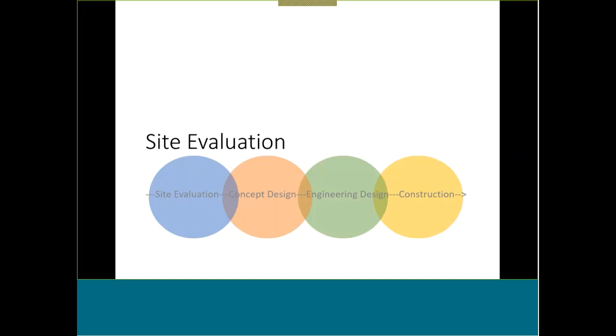So I think of site evaluation as being on a spectrum that includes concept design, full engineering design, and construction. The information that you're going to be gathering using our guidance and worksheet during site evaluation will naturally inform your concept design. You'll start to think, oh, if I see this parameter, I might want to choose this technique, or I might see higher wave energy, so I'm definitely not going to put this out there. And there's some feedback there. As soon as you start conceptualizing your design, you might realize you want to look at certain other things while you're in the field. So there's a continuity between site evaluation up to construction, where a lot of the information is going to be passed from one step to the other.